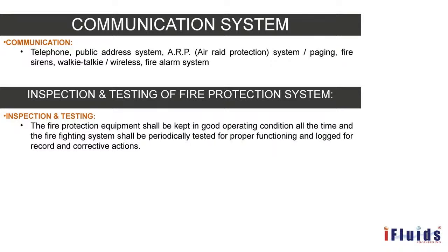If it is a foam tank, it has to be inspected externally every 3 years, and the entire tank has to go for internal inspection every 10 years. That is also stated under the fire water tank and reservoir testing conditions. If it is a fire water pump, it should be tested a minimum of 2 times a week.